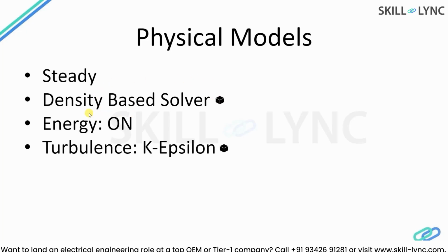Energy is turned on. So when we say energy is turned on, that means the energy equation is also being solved. In addition to this, we are also simulating turbulence by enabling the standard K-epsilon turbulence model.